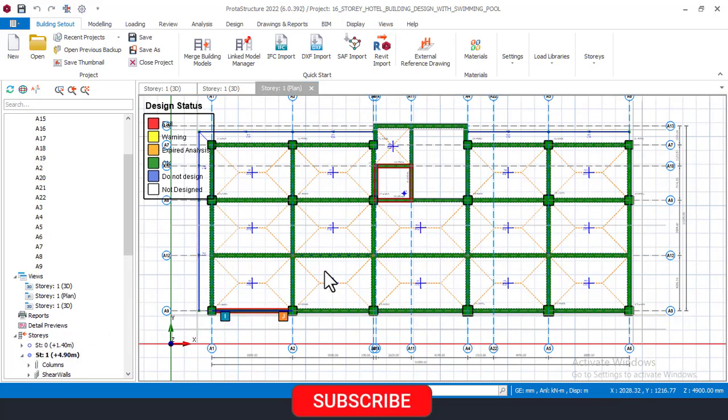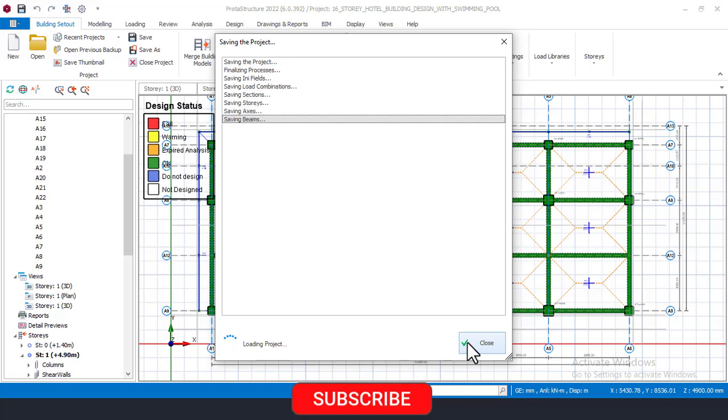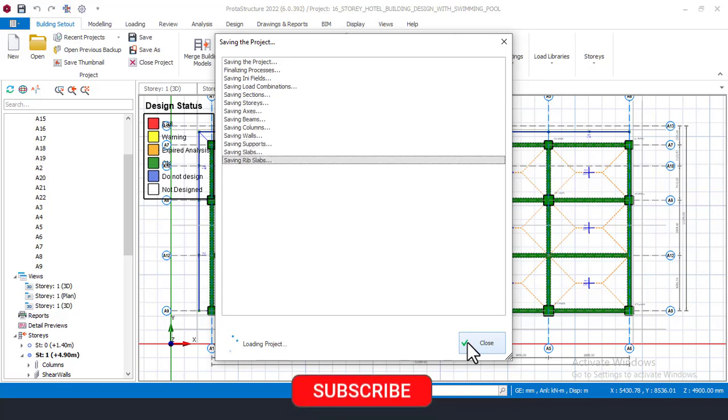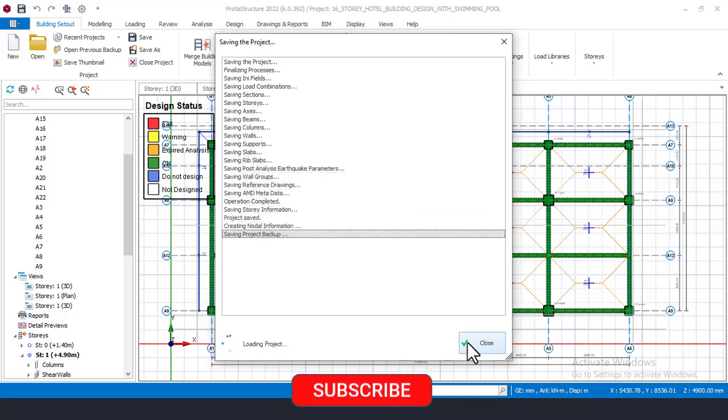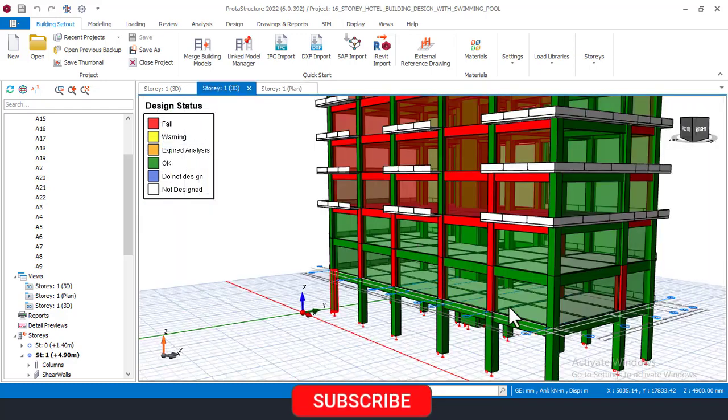Okay, so I will go right now and save what we have done so far. If you check our 3D view right now, you can see that all of story 1 is now perfectly okay, because we have checked the columns, the beams, and everything looks okay. We have checked with the software, and we have assigned our own reinforcement the way we want it. So if you check the 3D view right now, you can see that everything looks okay on story 1.